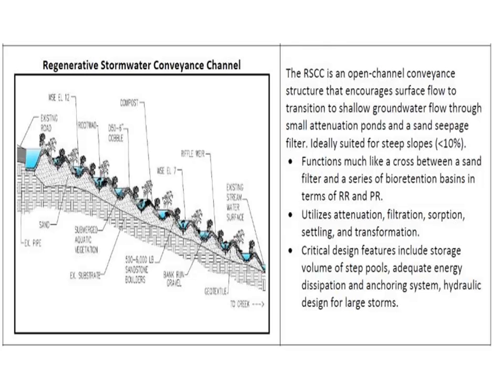But instead, if you make it a series of terraces, staggered terraces with a small puddle or pond at each one of them, then the water that's in the pond will continue to infiltrate after the storm event is over, and it essentially delays the travel towards the ultimate creek that's illustrated as the outlet here. So it has bioremediation advantages of filtering out whatever contaminants are in the water that's flowing, slows it down, and also is going to be more durable if it's constructed properly than a very steep slope would be where the travel velocities are high.